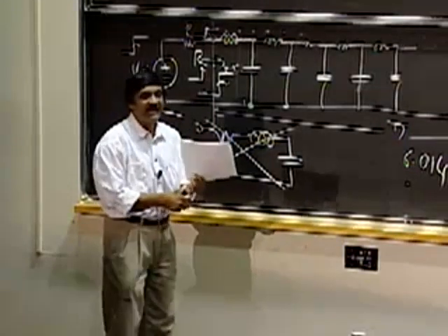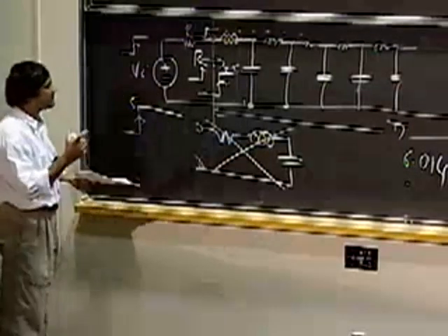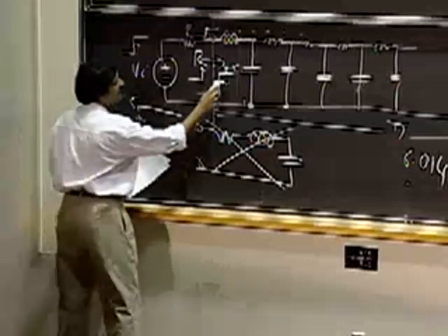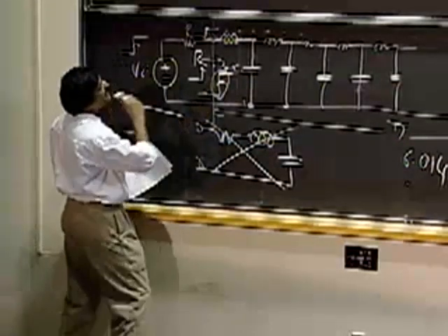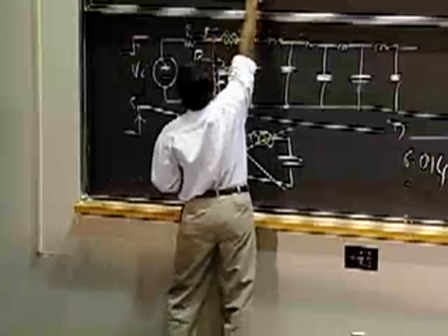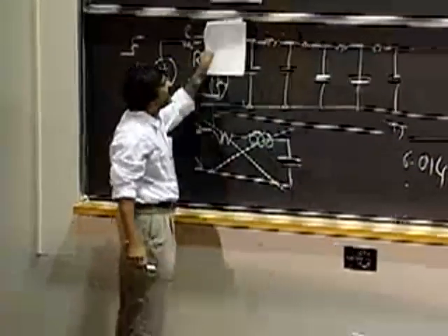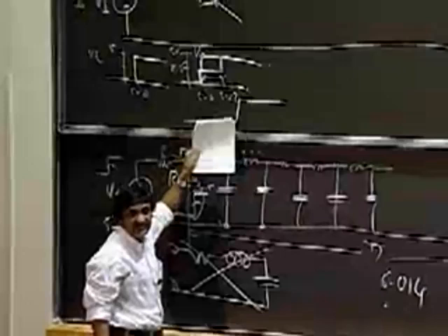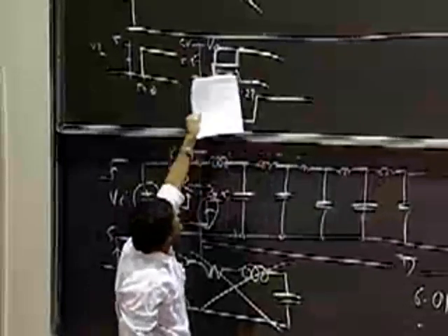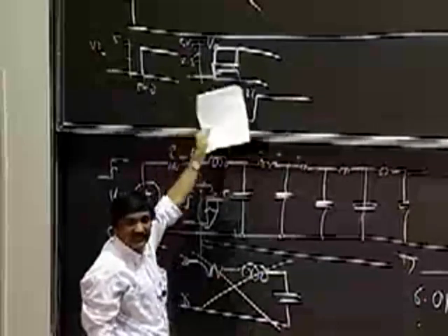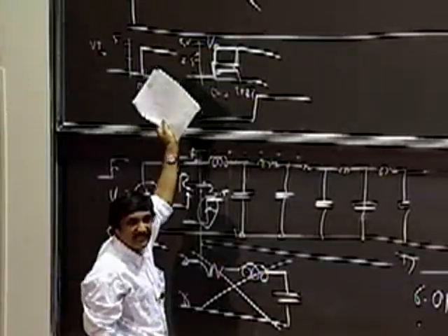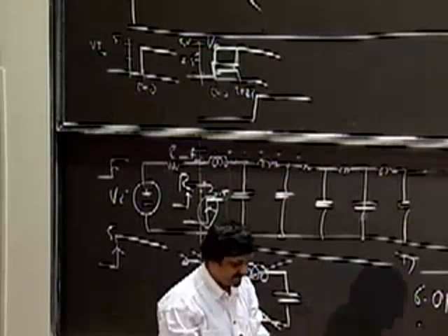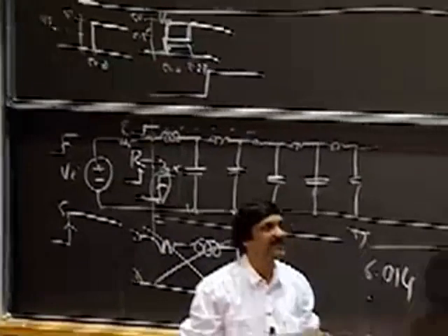So all I do is, if I arrange it such that my clock doesn't happen in this vicinity, but rather my clock happens late enough, then I'm going to sample and look at my signals only on the rising and falling edges of the clock, in which case I won't be looking at the signal when the signal is doing weird things. Okay, so a decent clock would also solve the problem.